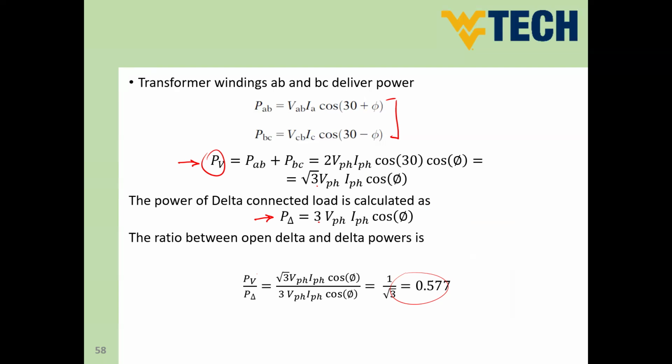Another thing is, all of the time we should consider a safety factor for our loading, but we have something else called load factor, which can compensate for this safety factor. However, experience-wise, guys, you may not find transformers in substations at rated load most of the time. So having reduced load on a transformer is not a big deal.